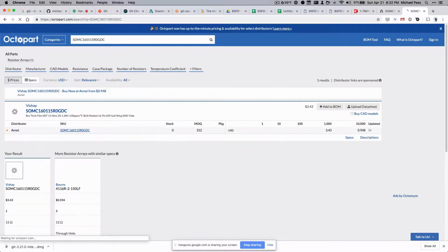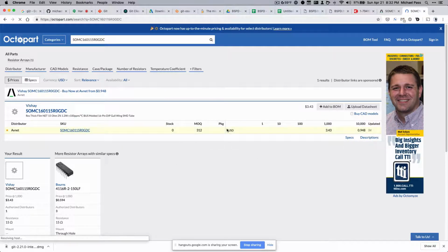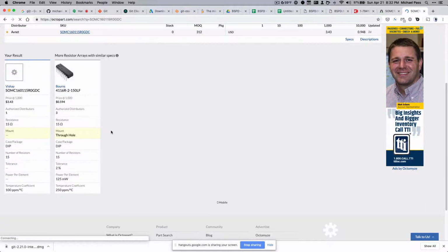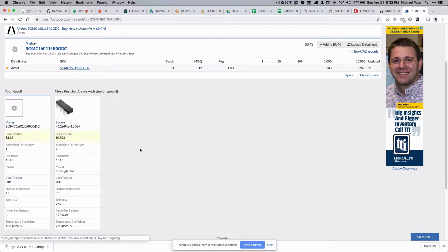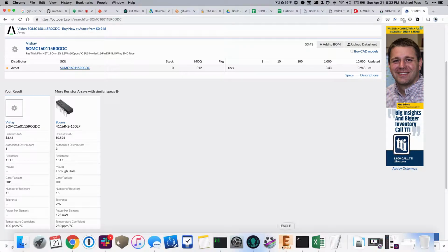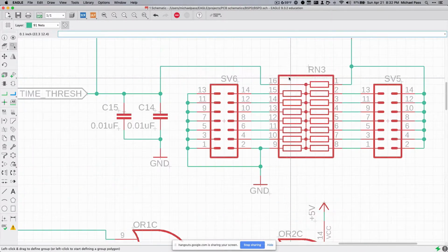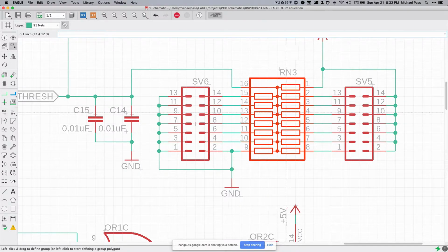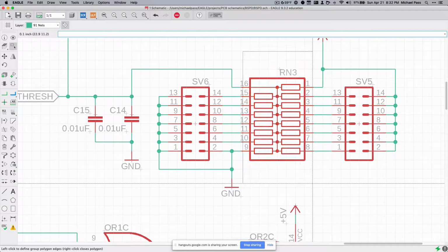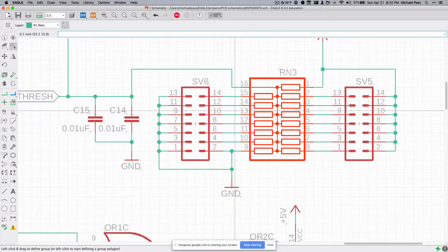So whenever we're filling out these actual part lists, we can find them. And actually, there's no stock here for this one, and it might not be this particular one. If we enter a product number that's this long, then it's literally just going to match this. In terms of how these parts get into EAGLE, I might have found something very similar to this in order to get it to work here, that has literally the same PCB footprint as another working part, but the manufacturer part number might have been different.